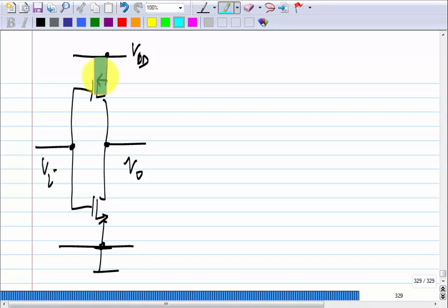So, essentially based on this you can make any logic gate that you want. That is another advantage, you do not need multiple stages. Let us say you want to realize a function like A times B or C, you can do it with a single stage with some exception. Maybe you will be able to realize the inverted form of this. So, you have to have a CMOS inverter following that, but besides that you can realize all logic functions with a single stage. That is not so with bipolar, and you also cannot make this with bipolar.